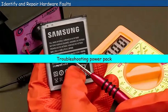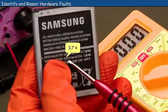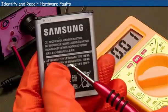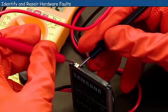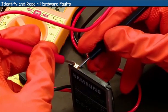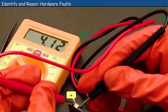Troubleshooting power pack. Usually, the mobile battery voltage is 3.7 volts or 4.2 volts. It is specified on the battery itself. To check the voltage, take a multimeter and keep the range as 20 volts DC. Connect the probe to the plus and minus terminals of the battery. If the multimeter shows the exact voltage as specified, then the battery is in good condition.